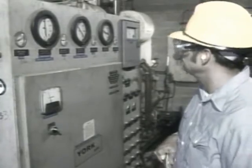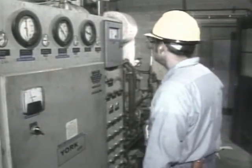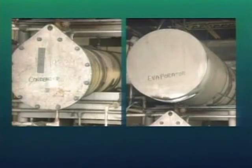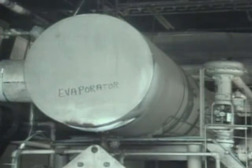Operators routinely check the temperature indicators associated with a refrigeration system. In most cases, there are temperature indicators for the substance being cooled and for the discharge of the compressor. The condenser and the evaporator may also have temperature indicators located on their inlets and outlets. These indicators can be checked to see if heat transfer is taking place properly. When refrigerant flow through the evaporator is too low, less heat will be removed from the substance being cooled. This will cause the temperature of the substance being cooled to increase.